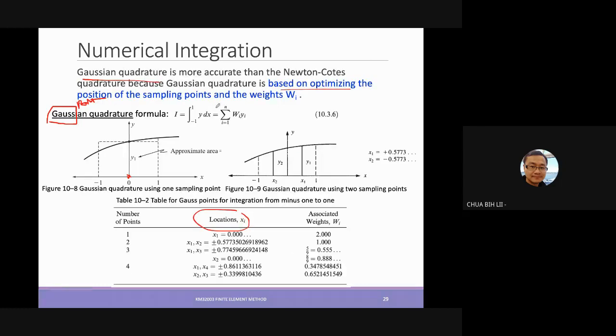area, right? So those points are where, when you do the stress analysis, the software will calculate, integrate, and do summations, multiplications at the particular point, or we call it integration point, Gauss point. Therefore, in some software, when you play around, sometimes you will see the terms integration point or Gauss point appear in your software. This is what it refers to, the locations of the integration points of that particular element, right?